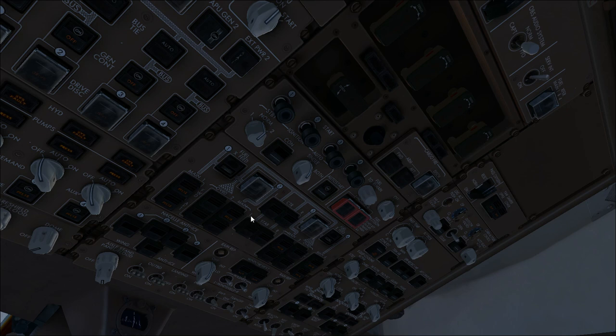This is pretty advanced, so I will leave it for the tutorial anyway, to give you a small insight about that. When the quantity of fuel in tank number 2 is the same or lower than tank number 1, and in the same way for the right side, so the fuel quantity in tank 3 is the same or lower than in tank 4, you have to modify the crossfeed valve selection by setting off the crossfeed 1 and crossfeed 4 and leaving the 2 and 3 on.